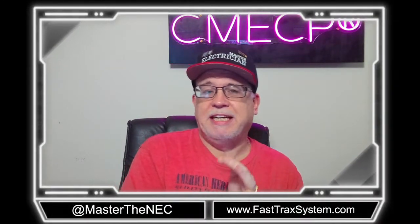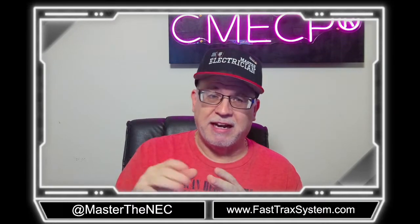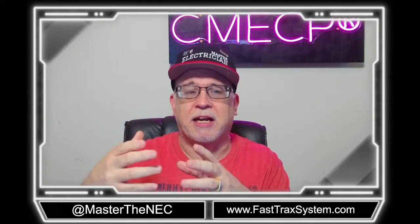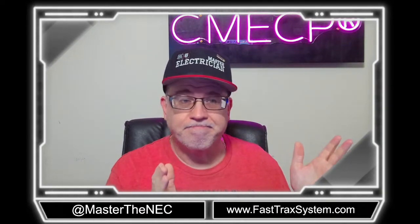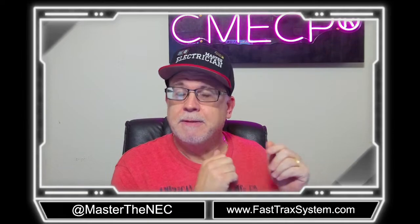All right, folks, let's bring it back to me. So the moral of the story here is, if I'm going to use a generator for a construction site, camping, as a standalone, separately derived system, I don't need grounding electrodes for it as long as I meet those conditions. Either the equipment or the receptacles are mounted on the generator and it's a cord and plug type of application, then I don't need grounding electrodes, okay? I don't want to use a floating neutral generator in a standalone application, okay?